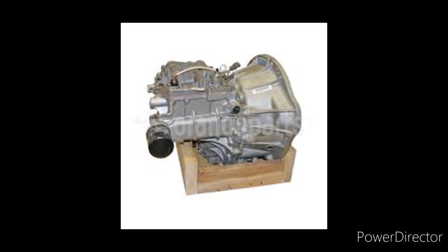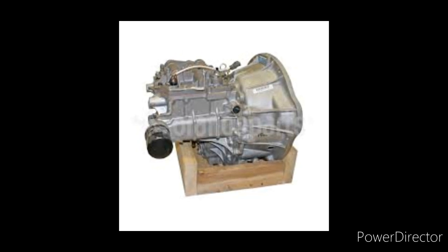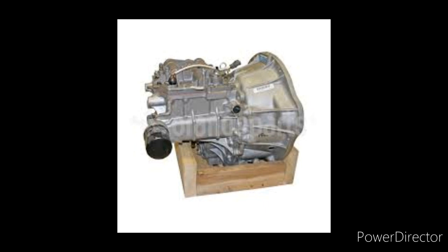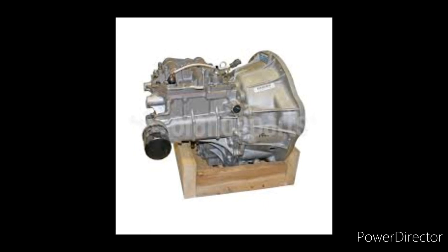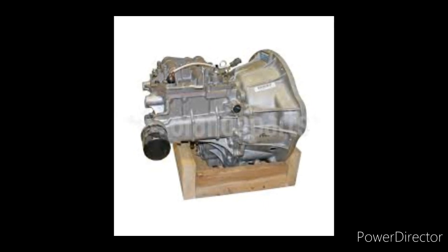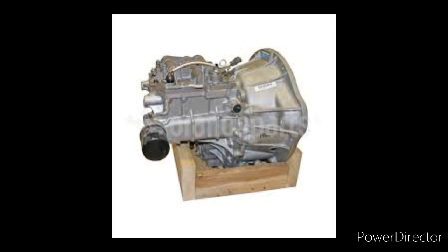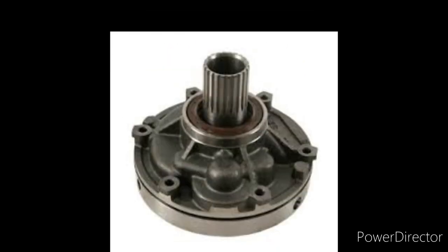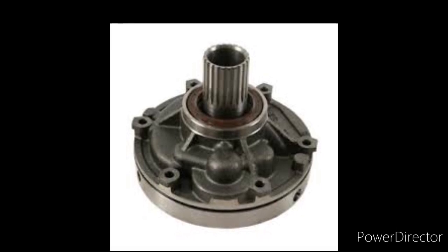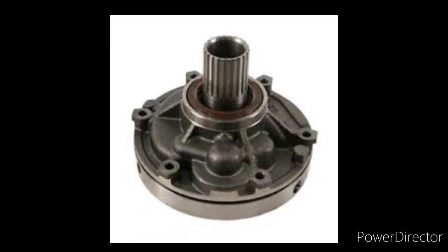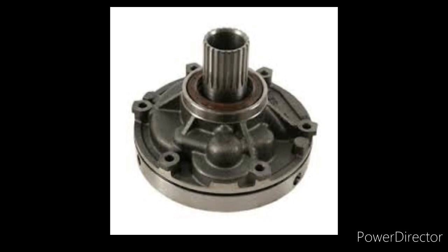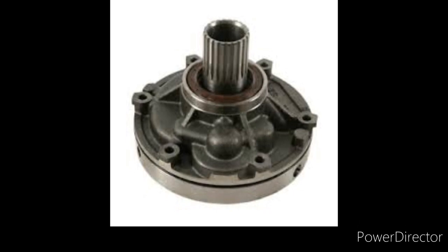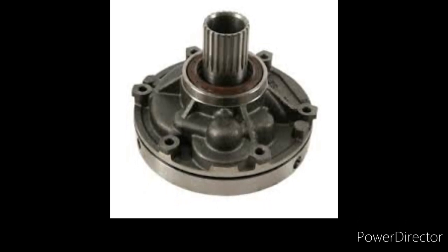Forklift transmission. A transmission is a set of gears, including a change gear and a drive shaft, by which power is transmitted from the engine to the wheels. Transmission is used only in engine-powered trucks. A transmission has the following parts. Gear-driven charging pump. This pump provides a continuous flow of cooled, filtered oil to the key transmission components.